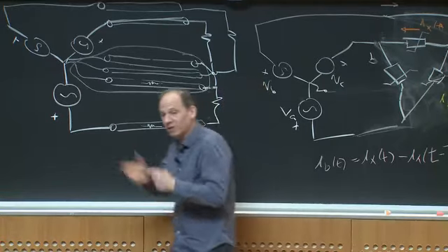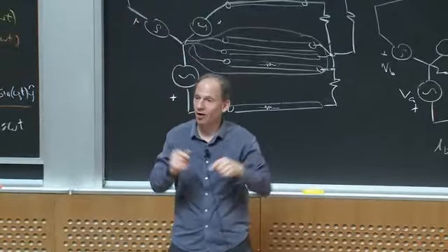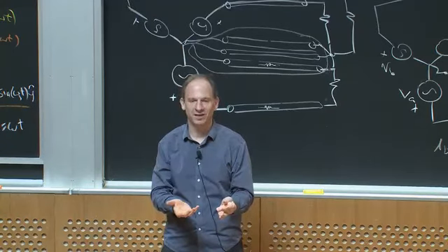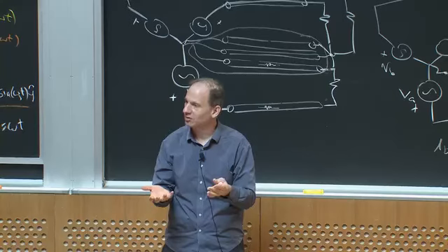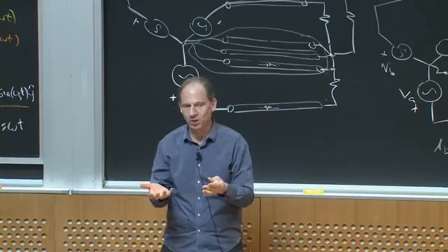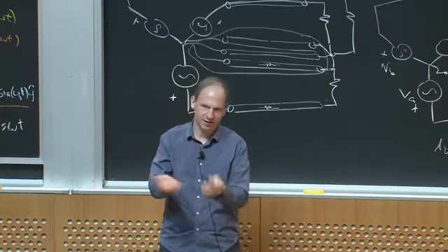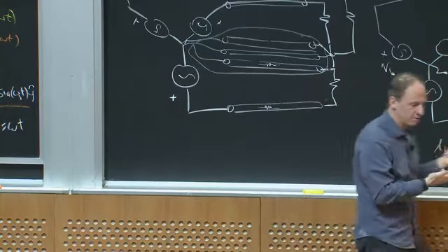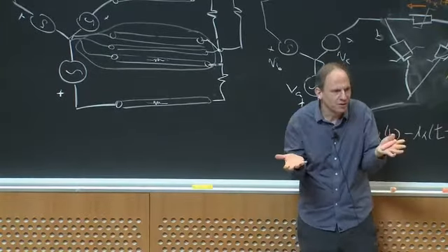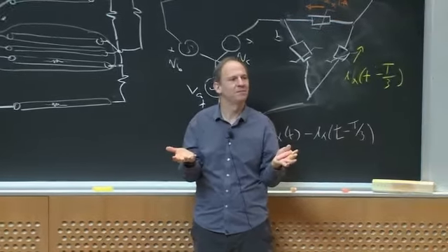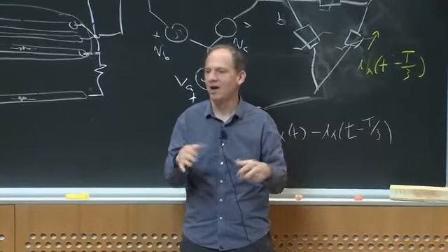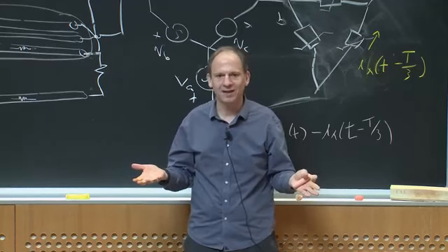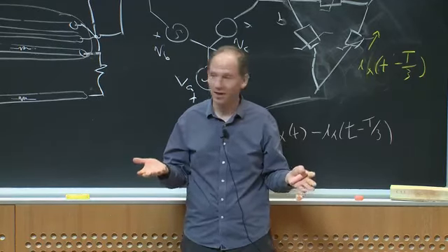Now you said, well, what if I had 4-phase? 4-phase also adds up to 0. And I can get all the benefits I talked about in 4-phase, except that I'd cancel different sets of harmonics, okay? So it wouldn't be quite as good in that regard, especially if I'm going to have things that don't have even harmonics anyways. But the beauty of it is that 3 is the simplest number that gives you the most benefit, okay? So people talk about higher numbers of polyphases, and people have worked on it. But in practice, you want the simplest thing that's really good, and 3-phase is it.